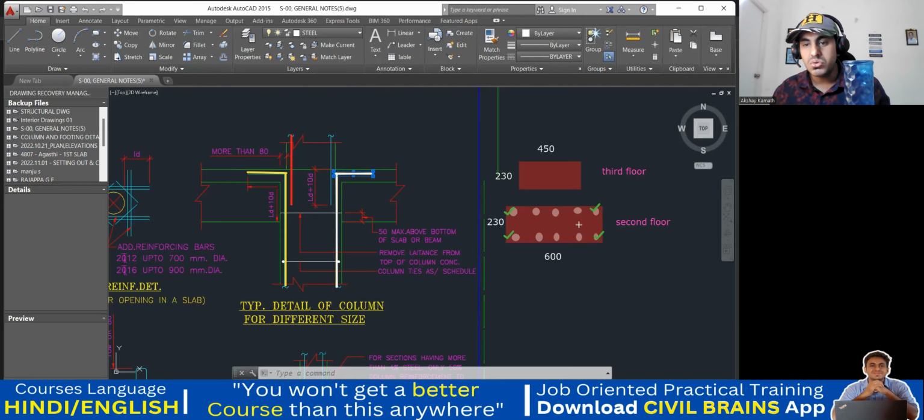So you bring these four bars like this, and then you take them inside the beam and slab junction. Inside you can insert it. How much does it have to be inserted? It is measured from this beam. This is a beam. From this beam, this much length should be Ld, that is development length plus 10 times the D. Got it? How much from here to here, whatever bend you're taking. So you have to calculate.